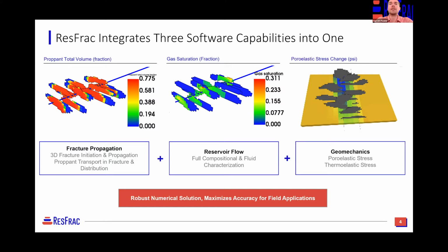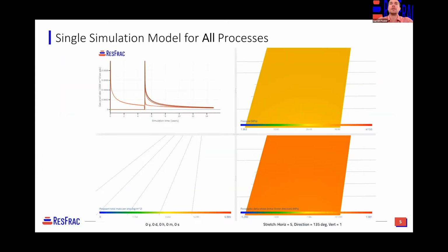The middle panel here would typically be a reservoir simulator. And then as you produce, that has impacts on the stress tensor, direction, and magnitude in the matrix. And so that's also fully integrated into the code. So it's all being solved together. So in every single time step, mass, energy, material balance is all being solved, which allows us to simulate complex interactions like this parent-child simulation that I set up as a demo.